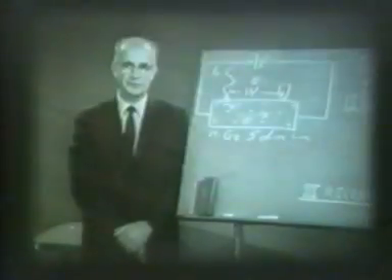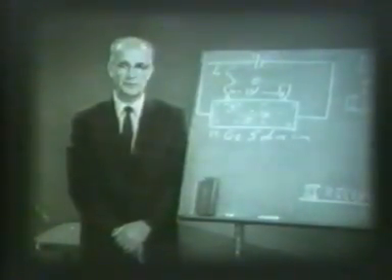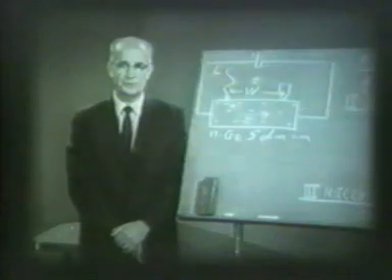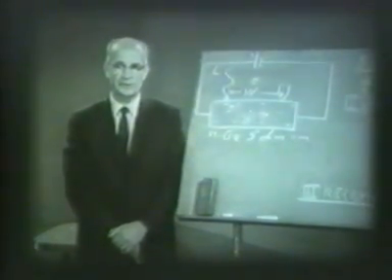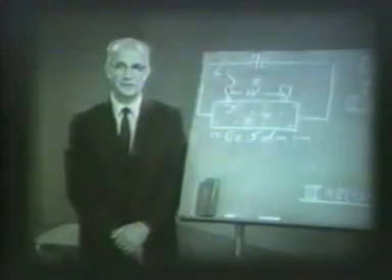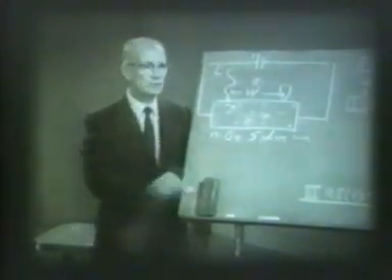To determine the electric field in the bar, we will later measure the voltage between these 2 phosphor-bronze wires. These wires are pointed and make small area contacts to the surface of the bar. The detailed nature of the 4 electrical connections to the bar is important. In particular, the right-hand point contact is also used as the detector of minority holes.